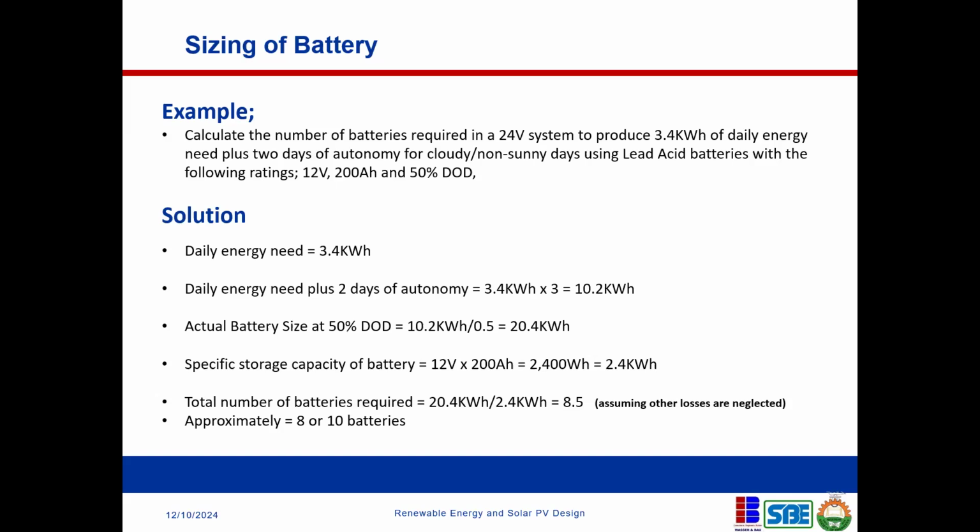Yes, in series now. You're correct. Exactly. So you need to pair two batteries in series. Sometimes it can be a little bit complex. You need to pair two batteries in series to arrive at 24. Yes, now that is series connection, you add. Exactly. So to arrive at 24 volts.